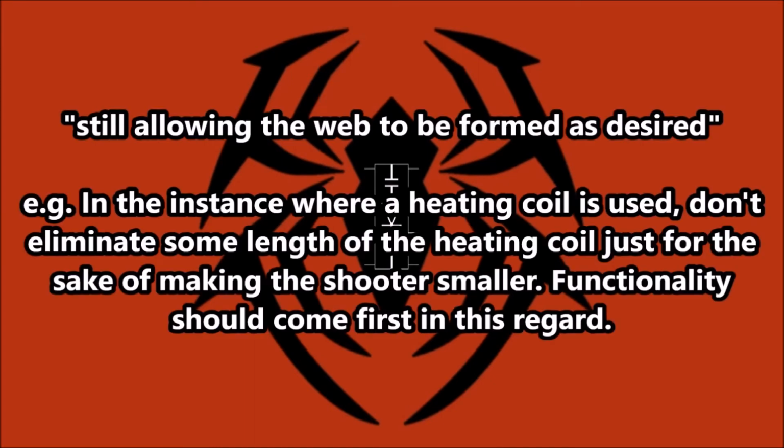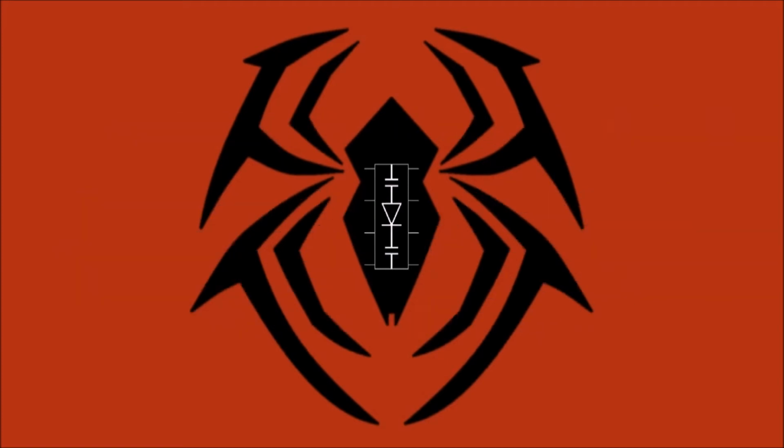Ideally, you'd want to eliminate tubing as much as possible so that you're as close to a configuration where each component in the fluid extrusion pipeline is directly connected to each other. This may require using extra resources for tubing and testing, and it may take quite a while to find the ideal amount of tubing, but it will save you a lot of hassle in the long run.